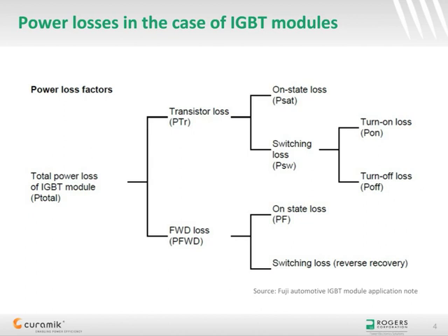Also, during switching on and off the load, current and voltage do not immediately turn on and off, but may overlap for a while. For devices with a slow switching time, this generates again significant switching losses. Of course, semiconductor technology keeps on improving and losses will be reduced in the next decades, but we can expect an increase in heat density as the size of the devices will shrink at an ever faster pace.